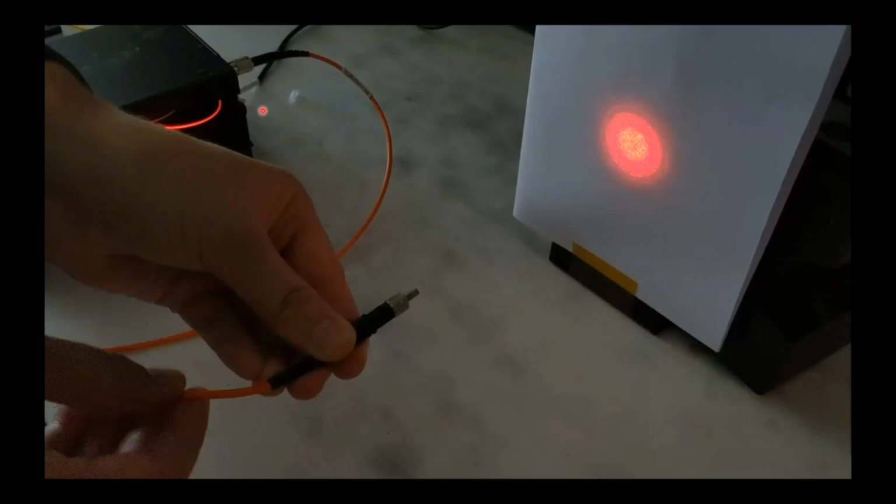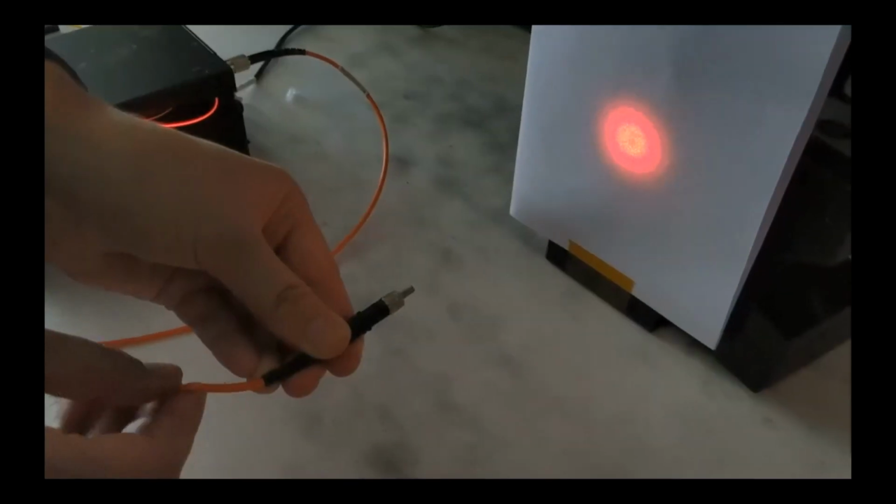In this experiment, we have a multimode fiber first, and then we'll show the single mode version. It's in a patch cable. And we're going to bend the fiber back and forth right behind the connector, introducing a bend in the fiber. We're viewing the output pattern on the screen, and we're going to see how the output pattern changes as we bend the fiber. So first, the multimode example.